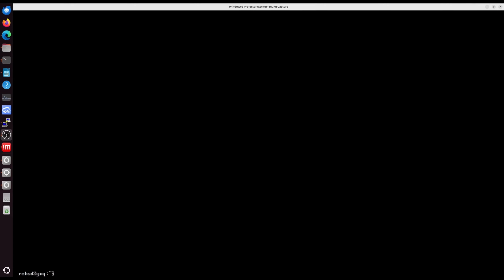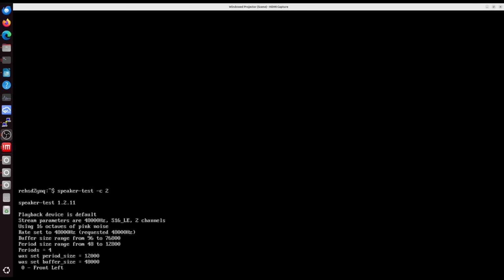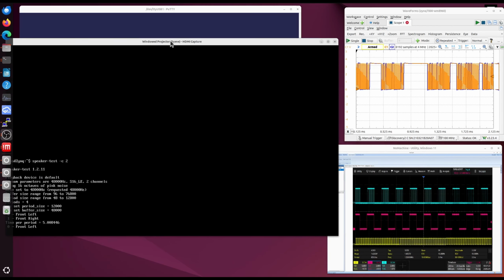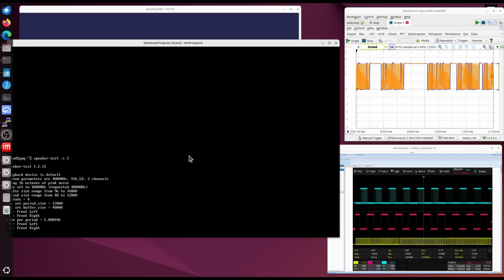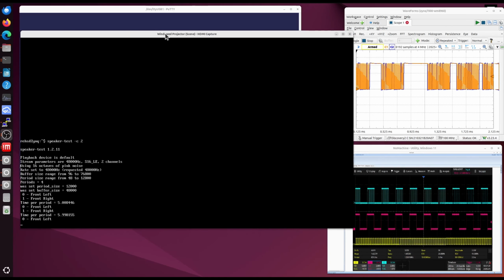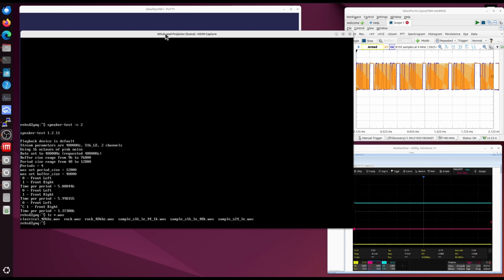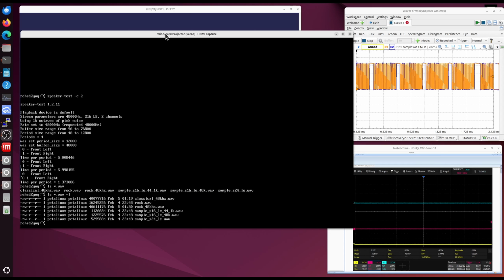But with that all done, then I can come in here and do things like the speaker test. Tell it to do a 2-channel test. And there I get that pink noise. And as it's doing that, there's activity, of course, over here. Getting out of that, I'll break out of it. I can then also do my aplay. That lets me play one of the WAV files, and I have a few different WAV files here. So if I look at that, these are the ones I have that I can work with.